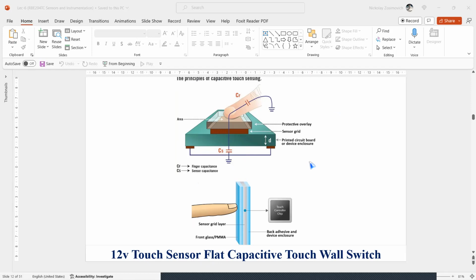The moving plate acts here as a coupling electrode between two equal flat electrodes and a readout electrode in the middle. All fixed electrodes are in the same plane. In the initial position, the coupling electrode is just midway between the two active plates, supplied by sinusoidal signals with opposite phase. In this balanced position, both signals are coupled to the readout electrode, where they cancel, resulting in a zero output signal.